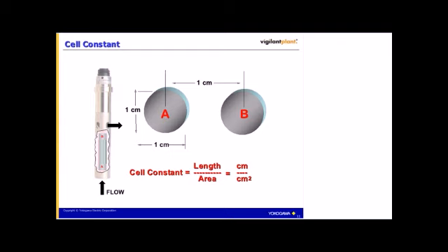Since we're interested in the measuring conductivity of the solution, the exact volume between the electrodes becomes very important. It must be well-defined and repeatable to be of use. Otherwise, we're not going to be able to tell whether the changes in the current flow we see are due to the concentration change in the process or just the random repositioning of the measuring electrodes. This volume between the electrodes of the sensor is defined by what is called the probe or cell constant, and determines what the effective measurement range of the sensor will be.